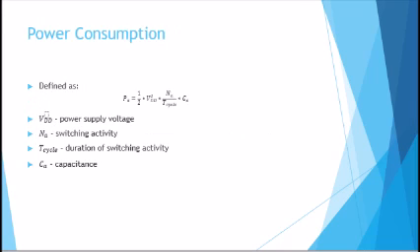As discussed earlier, the only time a CMOS-based digital circuit dissipates power is when there is a transition at the output. This is based off of the assumptions. First, that the power is dissipated through capacitance at the output. Second, that the current flows from the power supply voltage to the capacitor or from the capacitor to the ground. Thirdly, that the output voltage will change from VDD to 0 volts or the opposite, 0 volts to VDD. From this, the power dissipation can be defined as the following equation.